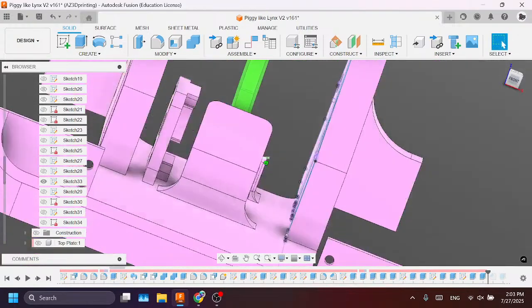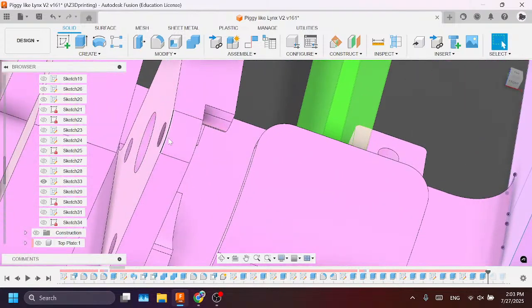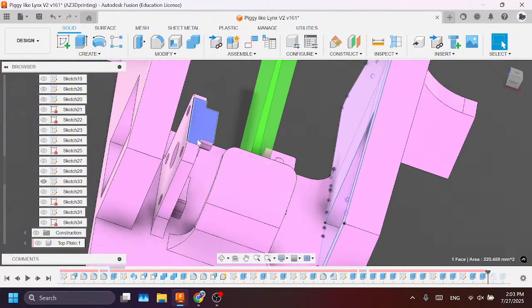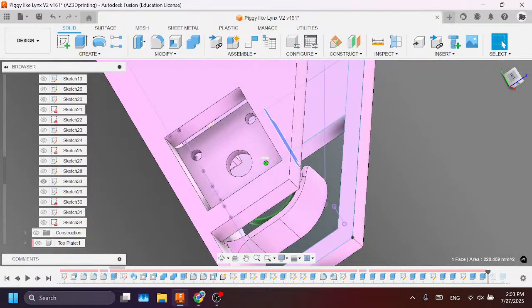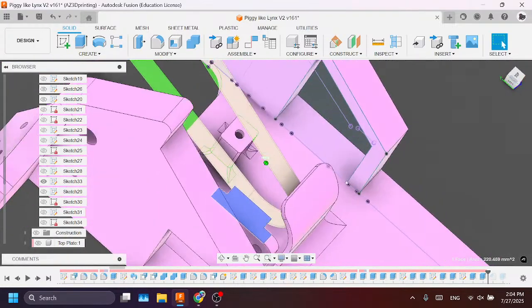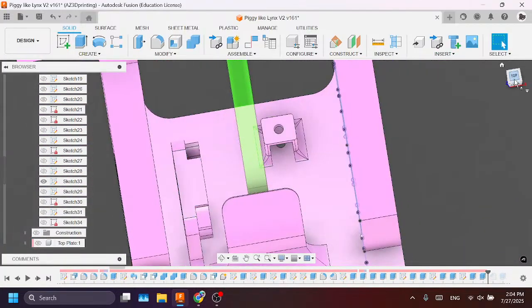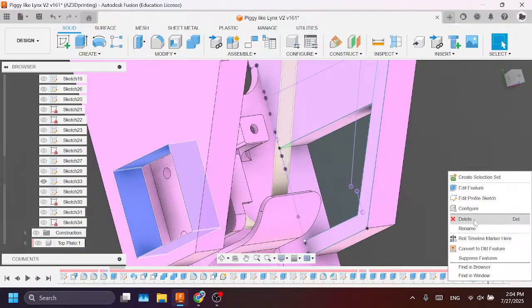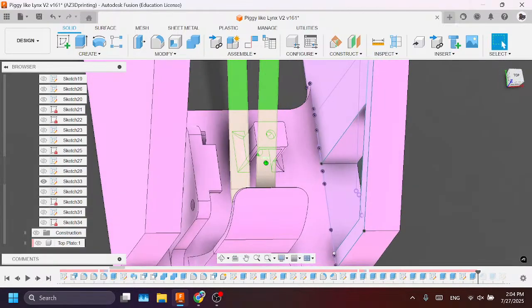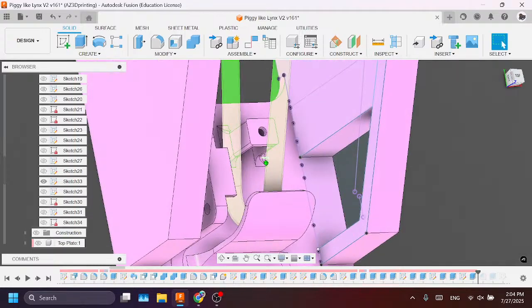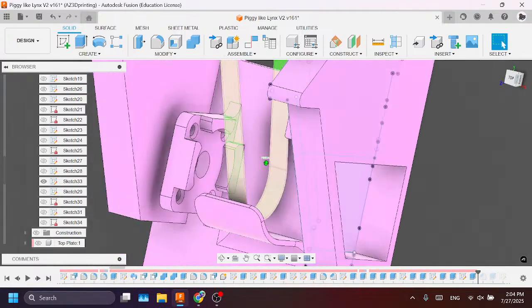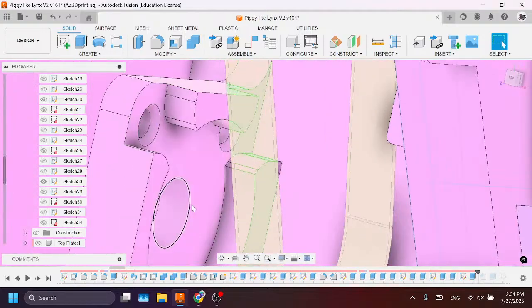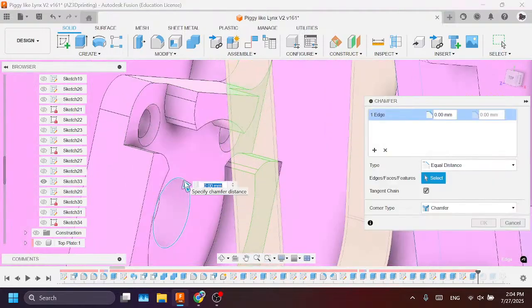And then what we're gonna do is, because we're gonna embed some M3 nuts inside this mount, which should, in theory, be a lot easier to assemble because you just gotta slide them in. So this guy can go away. What I'm going to do is, first I'm gonna hit a chamfer on this guy. So like 3, that's way too big. 2.